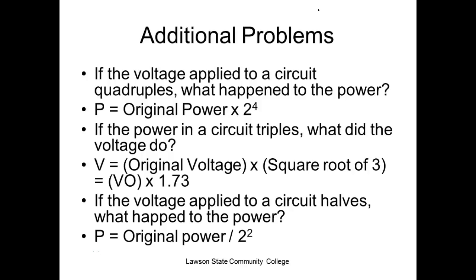So you have to teach two additional points. As soon as you hit circular move, it's ready to teach this point and that point. Your entry point would be the last one you teach. If you come in here with a linear move, stop it, and then say circle move, it pops in two points. You have one, you have the other.